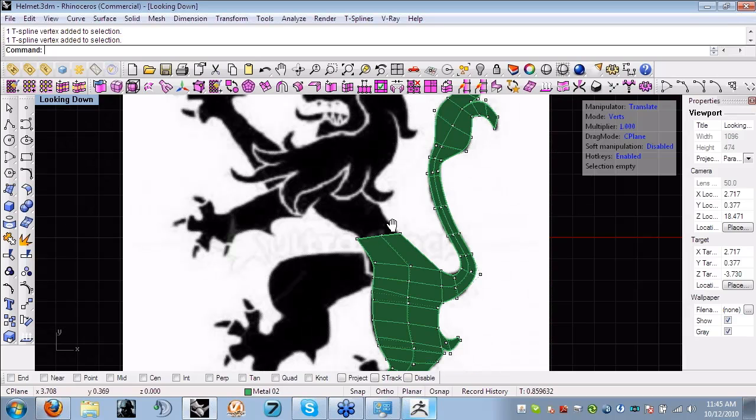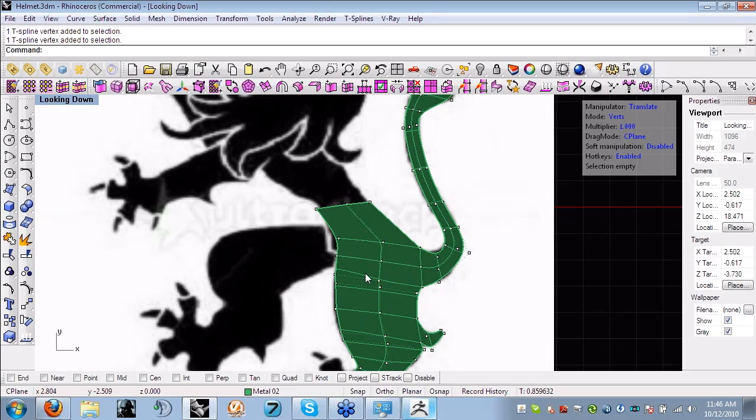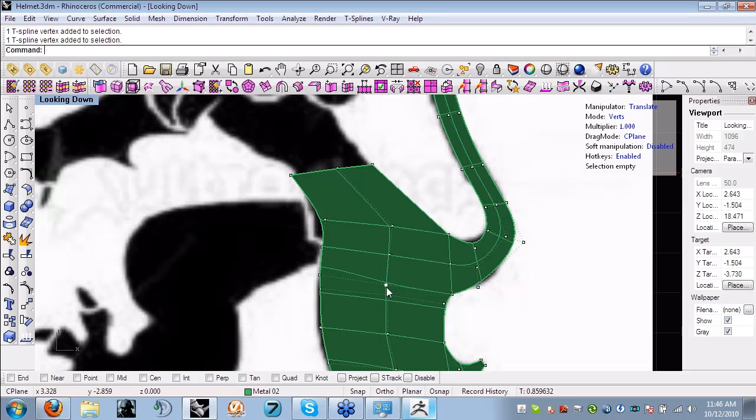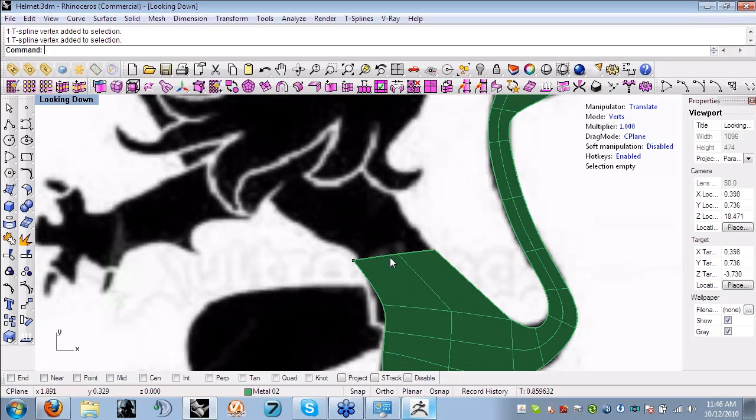It took some practice. This is in other software packages. This is known as extrusion modeling, and I think T-Splines shares a lot of modeling techniques with subdivision modeling, and in surface modeling, everything's about the curves. So it takes you a little while to understand that this is a different process of modeling that works with surface modeling. So while it is completely compatible and you can work that way, once you sort of wrap your mind around this whole process of extruding and making faces where you need it, it's not that technical.